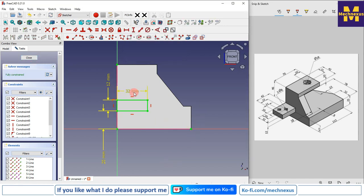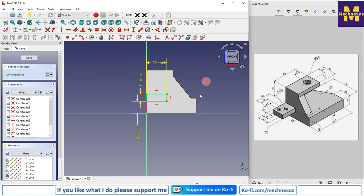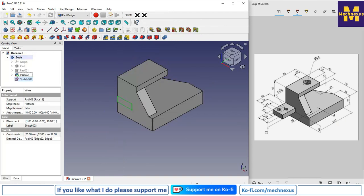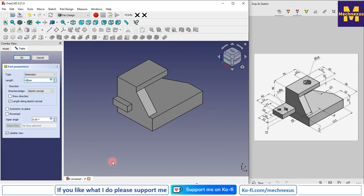Now I will move the dimensions so you can see it. This is a 20, 12 and 32. We will close it and we will pad it to the 42 mm. So click on the pad and give the 42 mm.